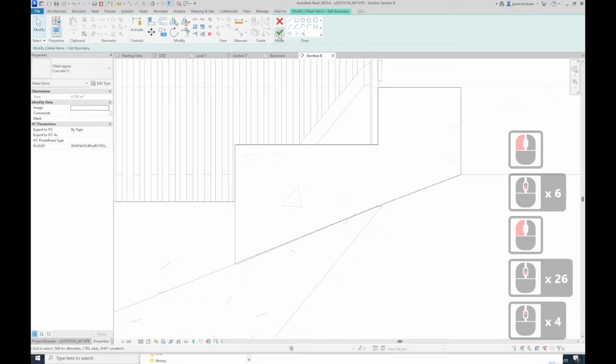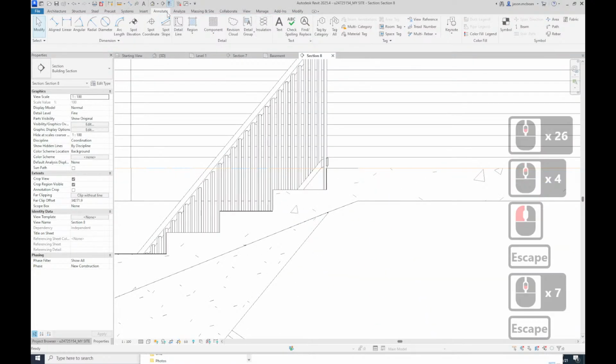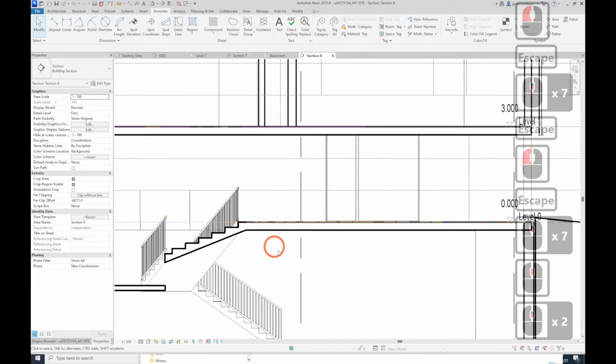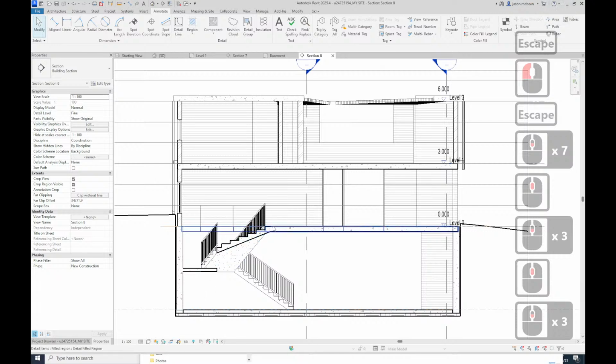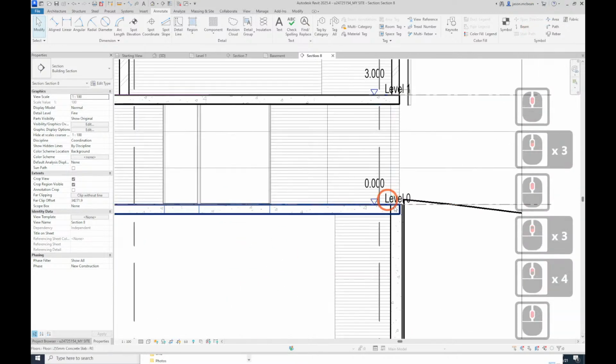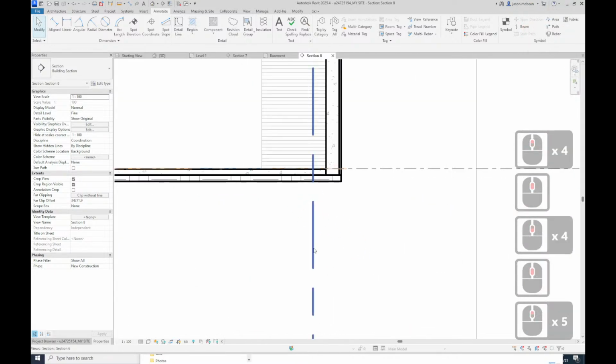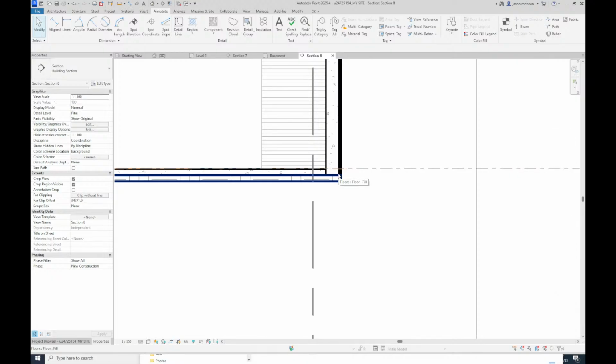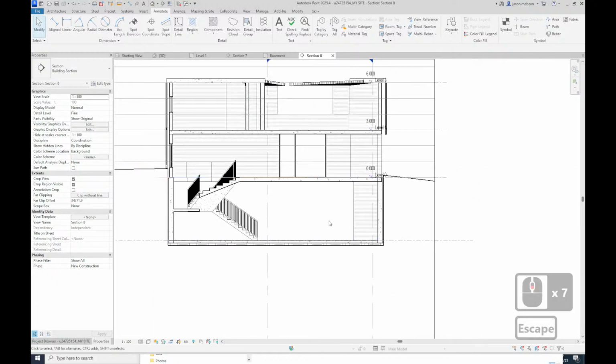But those are just annotations, right? Annotation. Okay. Watch, it's not on the actual model, it's just annotations, but we'll never see it on the view. So now you're seeing it correctly. This connection, where you put your footings in, don't model it. You draft it. Otherwise you're going to be spending months putting the footings in, and in this section you're just showing the footings, because you don't see the footings anywhere else. Draft only and then section.